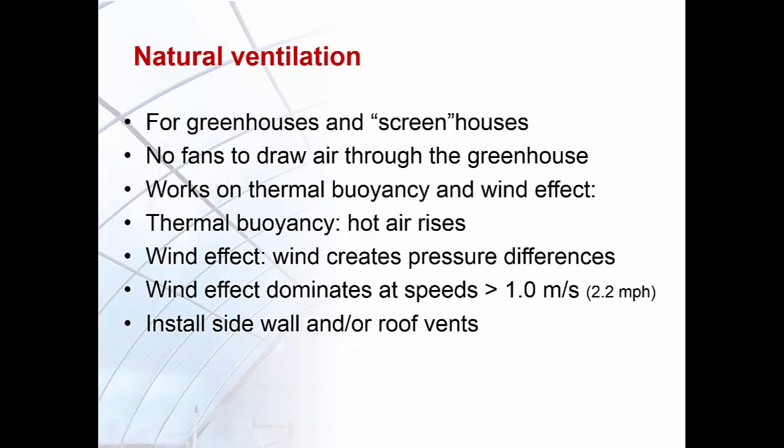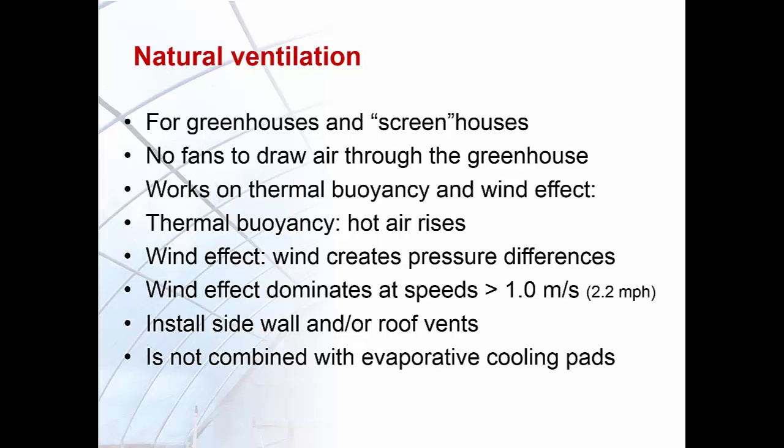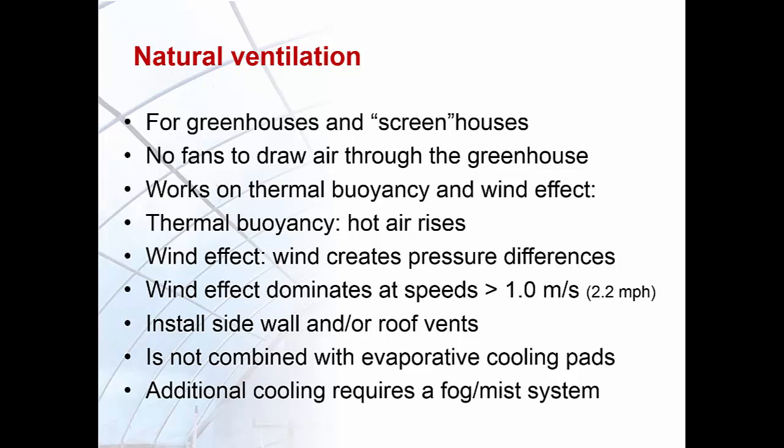Growers need to install sidewall and/or roof vents to achieve proper natural ventilation rates. A natural ventilation system is not combined with evaporative cooling pads. If additional cooling is required, a fogging or misting system must be installed.